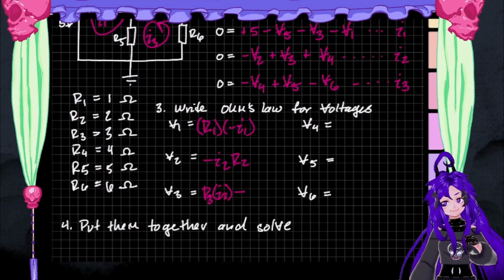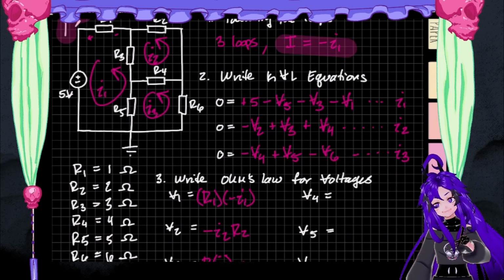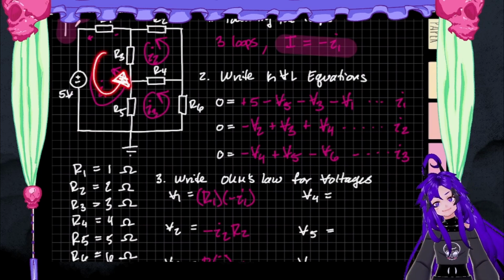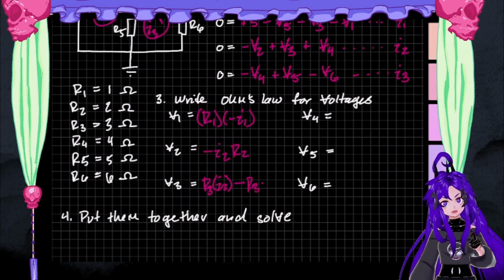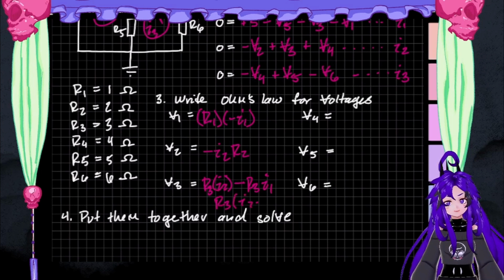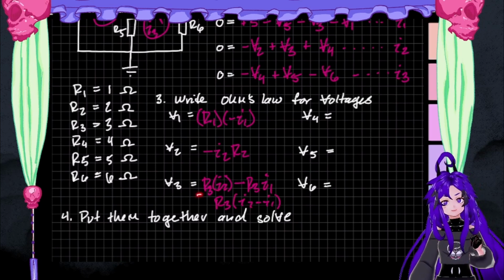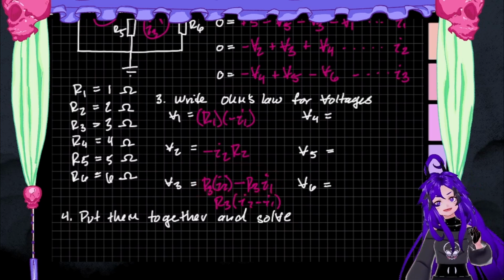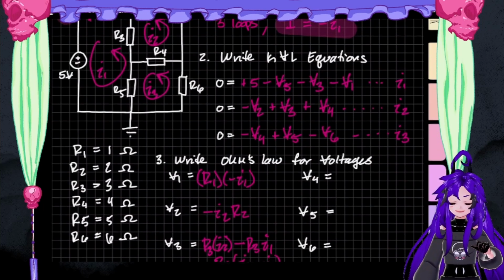And then we're going to subtract the current that's hitting at the negative direction, which is going to be I1, so it's going to be minus R3 times I1. And yes, you can factor the R3 out and just write R3 times I2 minus I1. But sometimes it's a little bit clearer to write both terms out to figure out where this came from. Why did we do this?